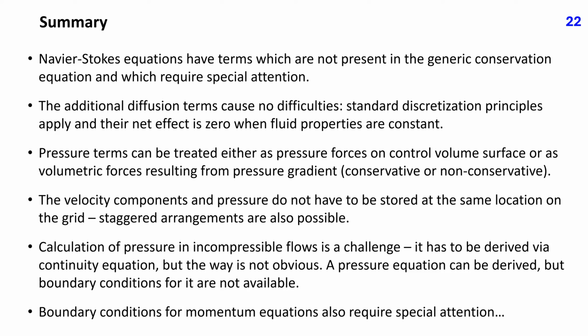Pressure terms can be treated either as pressure forces on control volume surface or as volumetric forces resulting from pressure gradient, corresponding to a conservative or non-conservative approach. The velocity components and pressure do not have to be stored at the same location on the grid. Staggered arrangements are also possible.